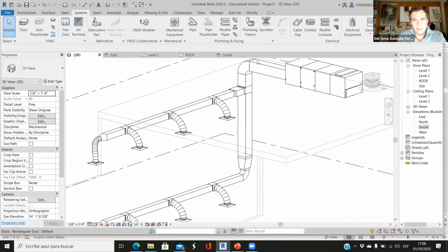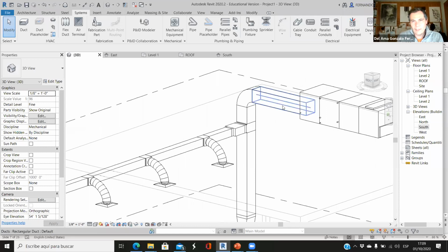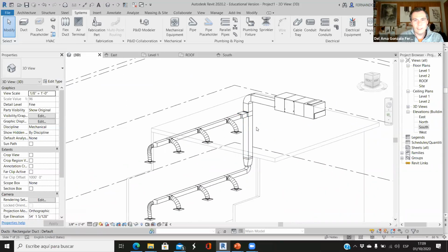So I have simplified the ductwork, and now it's better, because we are reducing the time. Connecting all these ducts in Revit takes a couple of minutes, but in real life, people have to cut the right length, then connect the duct and the elbow. So it takes a lot of time. So the fewer the fittings, these elements, the better. Designing simple Revit ductwork is easier than complicated Revit ductwork. So we have to reduce the elements, and this is what we have done here.